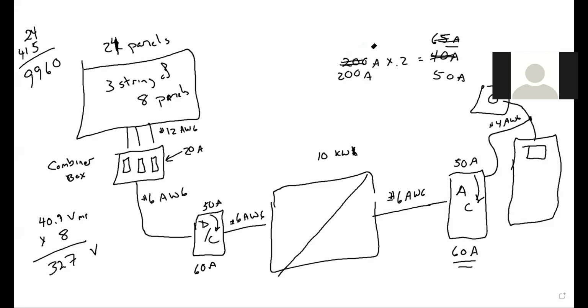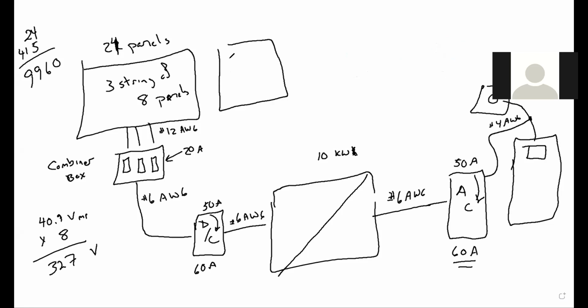And I'm anticipating you guys are going to review this several times because I'm jumping over it pretty quick. So what am I going to do? I'm going to anticipate I've got to probably have a supply side connection on this. Because of the size of this, I'm actually going with 2 arrays. So this is going to be 3 strings of 8.